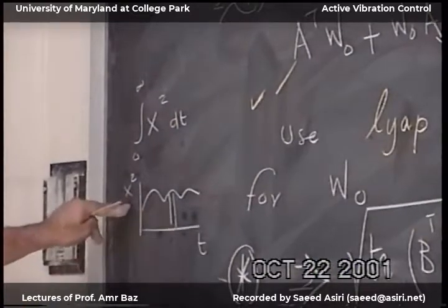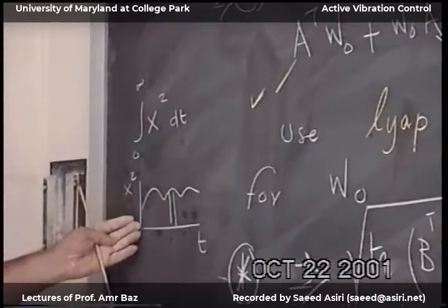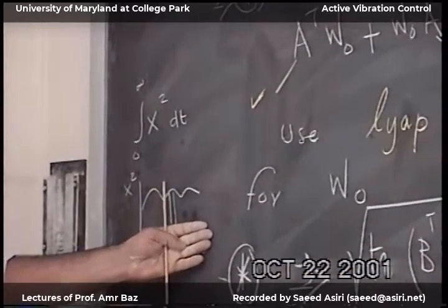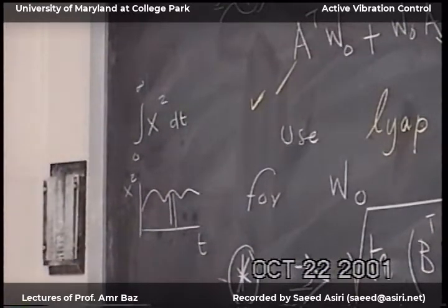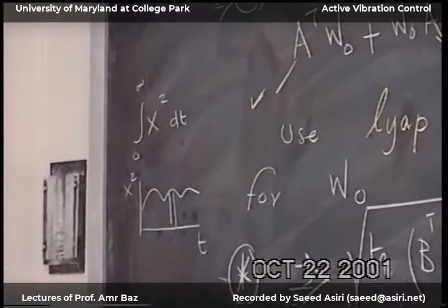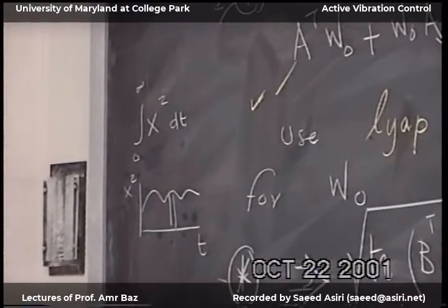So now I take the norm, which is the second norm, which is indicative of area under curve. This is one performance index which we covered in all these three controllers. The trace operator came in the general case of the LQG when we designed the LQG controller.